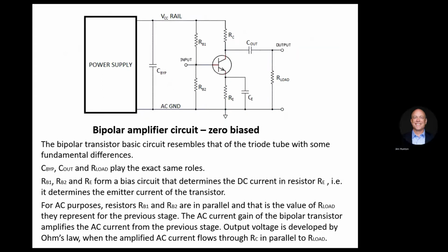This is the bipolar transistor. Well, we said a bipolar transistor is a current amplifying device. So we have to set up the operating point, not by voltage on a grid, but by current through the base. Well, to put current through the base, we need a divider here that sets up the voltage. At this point, there's some DC voltage. It drops to this point, 0.7 volts, which is a diode. I'm waving hands a lot. And then this determines the current here. So this is how we set up the bias, the operating point of a bipolar device.